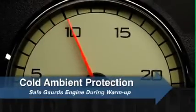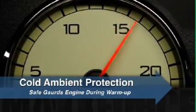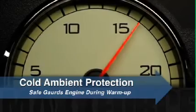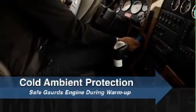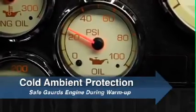Cold Ambient Protection, or CAP, safeguards against engine damage by raising RPMs during engine warm-up in cold weather conditions. Allow the engine to warm up for 5 minutes and verify that oil pressure is above 20 psi before driving.